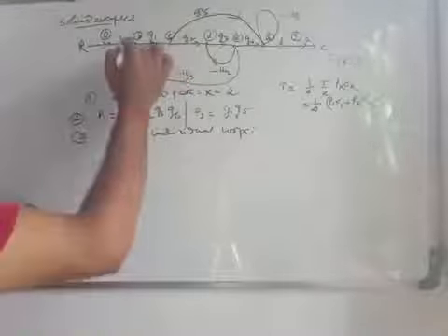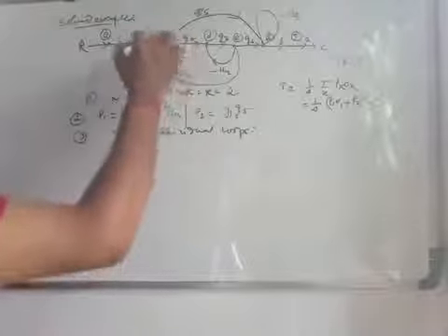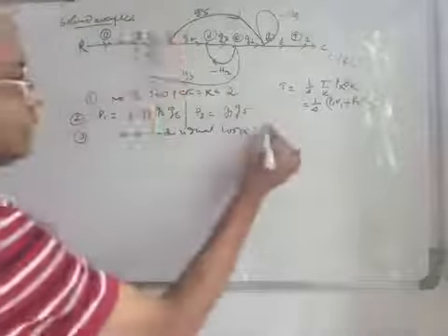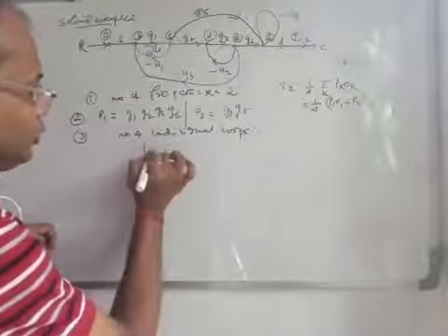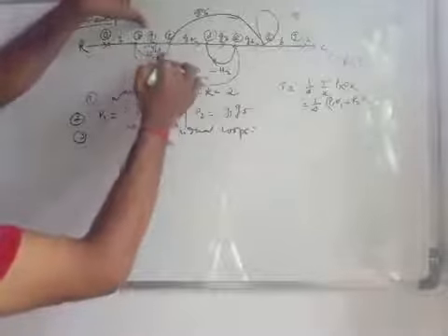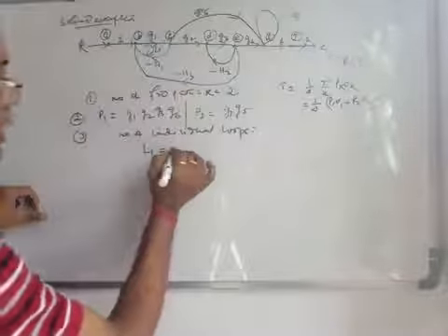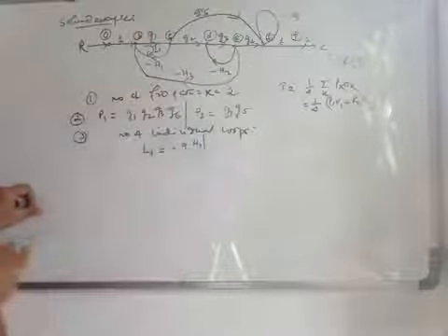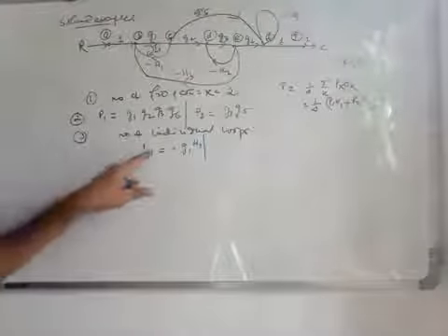B, C and B, directed in this direction. So this could be loop 1, with loop gain. What is the loop gain? This is G1 into minus of H1. So minus G1 H1. This is loop 1 with gain L1.